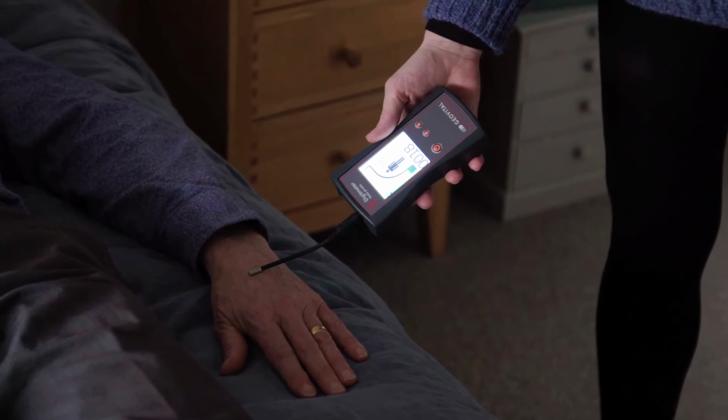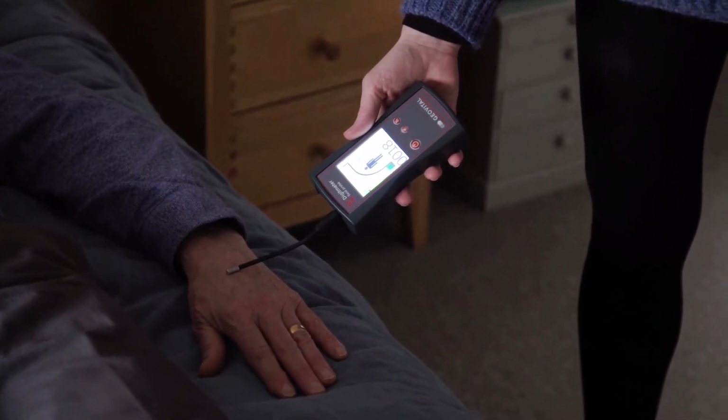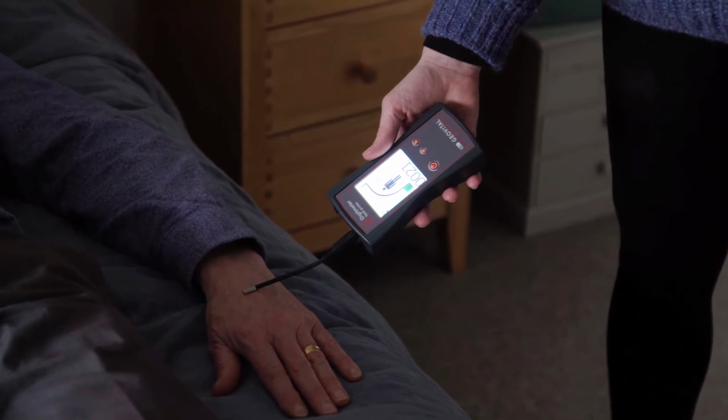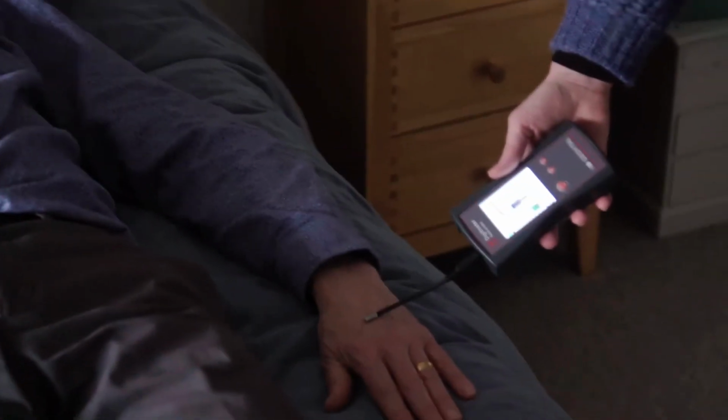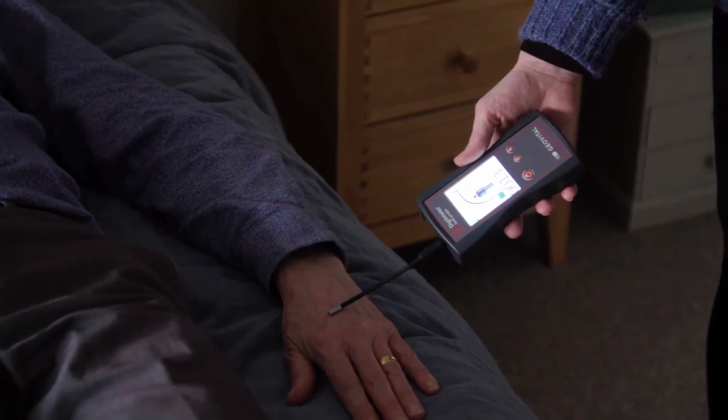Right, so we've taken the high frequency reading, so now we want to check the low frequency. And for this, I'll lay on the bed and we'll measure it with a low frequency meter. The reading fluctuates between 11 and 20, which is a really good result. We want to be under 50 volts per meter. So we've effectively shielded this room from high frequency and low frequency. Before we shielded the room, we were getting readings of 1300 volts per meter. So it's a massive reduction.